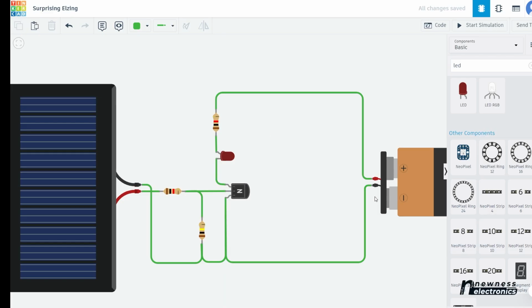Now, I want to show you something. If I connect my circuit like this, it is a simple transistor as a switch. If you remember, this is a simple transistor as a switch circuit, where the base control circuit now is coming from a solar panel. And if there's a supply into the base from here, this transistor is meant to turn on this LED,